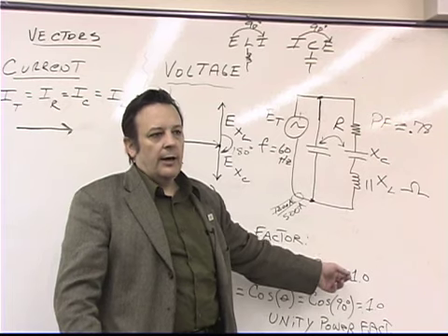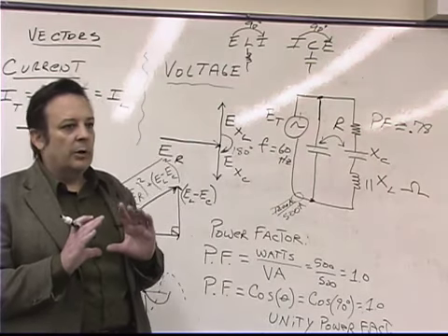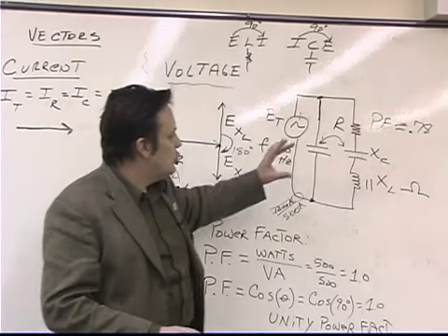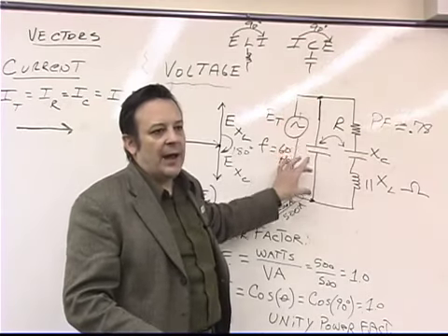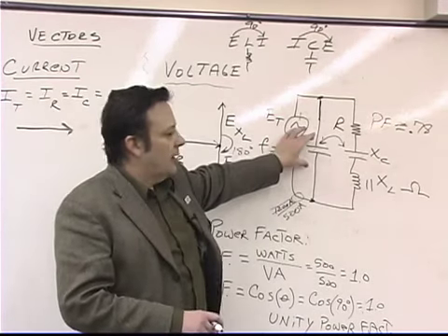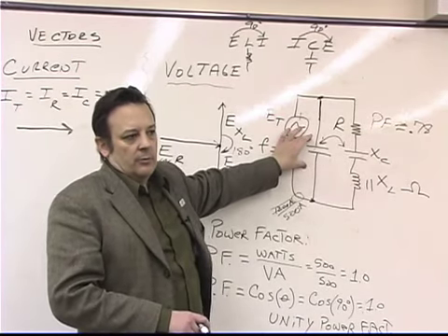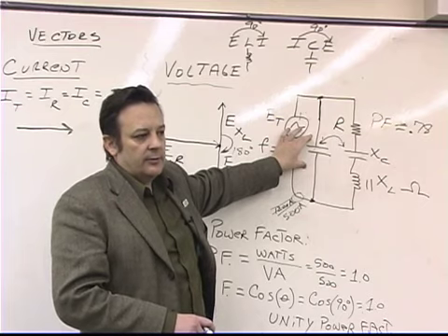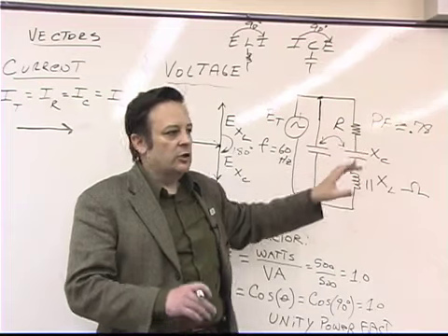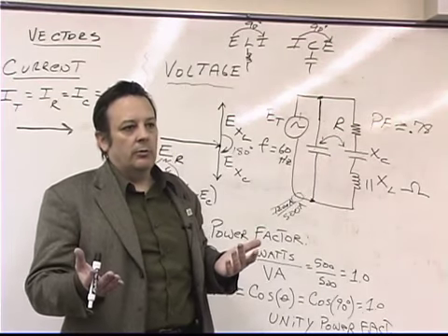And the reason that it's a little bit more sophisticated or difficult than just hardwiring in a capacitor is because the amount of farads or the amount of capacitive reactance that needs to be in parallel with the load is going to change every time you turn on a new load.